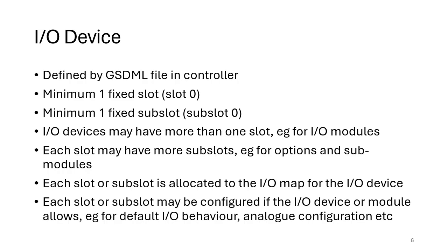Now, the I/O device is defined by a GSDML file. So the GSDML file is provided by the I/O device vendor, and that's used in the controller's configuration software to actually configure the I/O device.